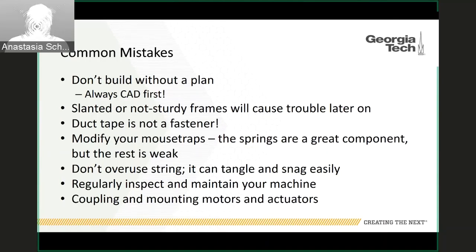Another mistake that we see is in coupling and mounting motors and actuators. So we've seen people hot glue motor shafts to wheels, and surprisingly, that doesn't work very well. So like I've said many times, it's always best to draw something up in CAD, just make a quick little motor coupling and 3D print it out, or buy one on McMaster. That's much better than being lazy about it, because that'll come back to bite you later.